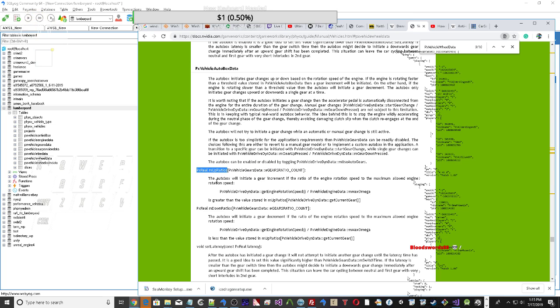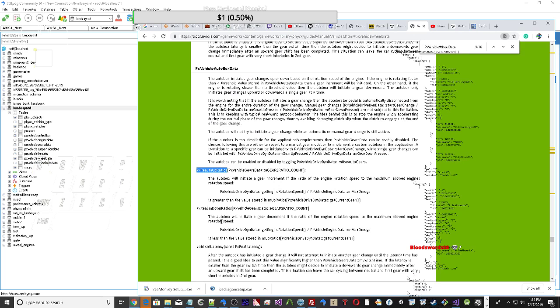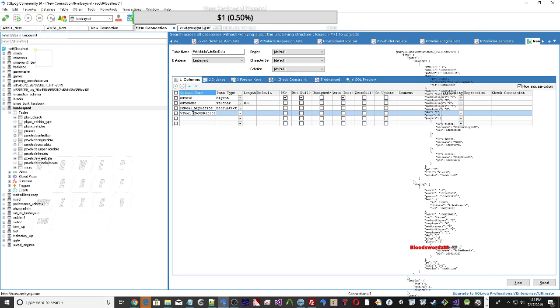Figure 2. Suspension limits and suspension raycasts. The suspension force from each elongated or compressed spring is computed and added to the aggregate force to be applied to the rigid body. Additionally, the suspension force is used to compute the load that is bearing down on the tire. This load is used to determine the tire forces that will be generated in the contact plane and then added to the aggregate force to be applied to the rigid body.